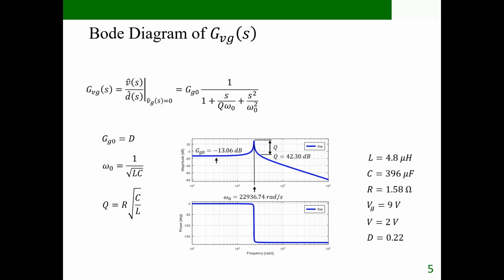This transfer function is important because it describes how input voltage disturbances propagate to the output. If your upstream supply introduces ripple, switching noise, or load interaction disturbances, this diagram tells us exactly how much of that noise will reach the output. Later, when we design the compensator, and especially if we use feed-forward, this transfer function becomes key for improving line regulation performance.